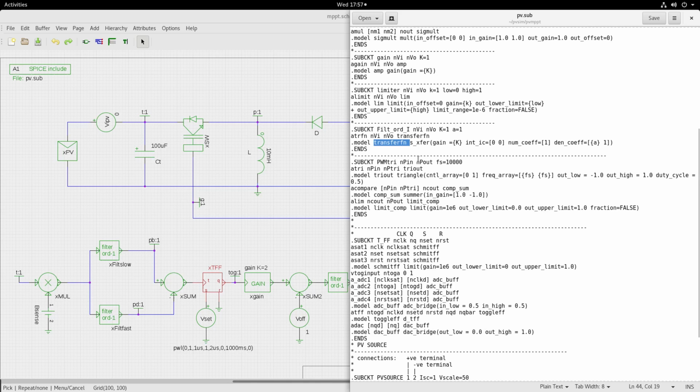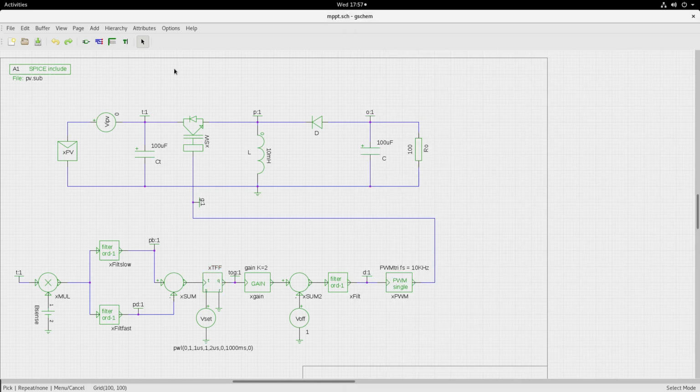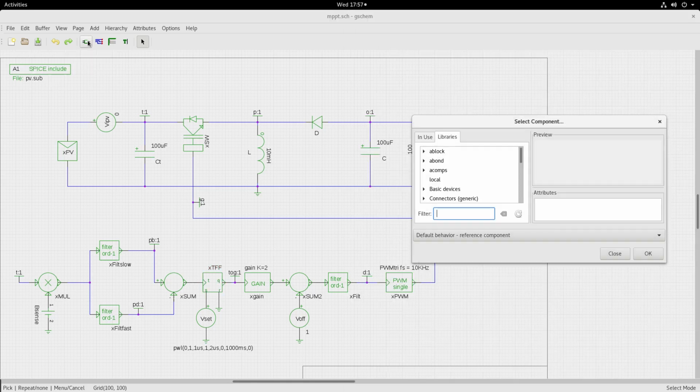So in this way, first order filter is done. And the symbols for that, like before, I have already done that and kept, and then called it from within the symbol files. So you will see that when I open this block in the A block directory, I have the filter symbol.